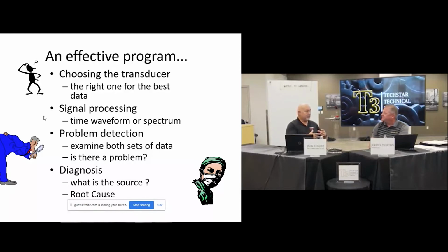And we'd pull it, cut it apart, and look at it, and it just had all types of divots all in the outer race. And it really had not a load on it. It was just more for locating the shaft.